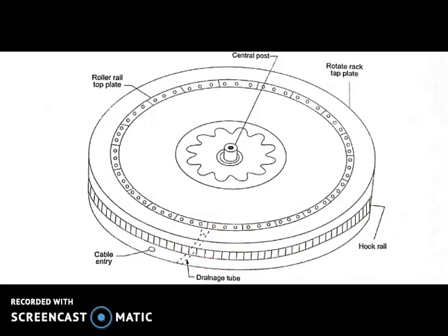The tub is a welded bracket structural member. The tub provides a large load bearing surface, as during operation the whole machine rests on the tub. The ring gear is rigidly attached to the base. At the center of the base, there is a central post which carries a central pin above which the turntable rotates. A roller race unit is placed on the top of the base, which carries the total weight of the turntable and also permits the rotation of the turntable.